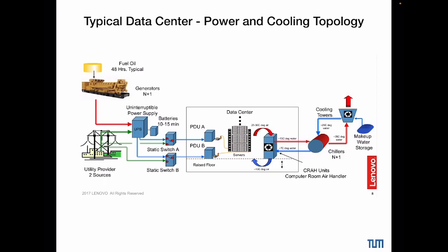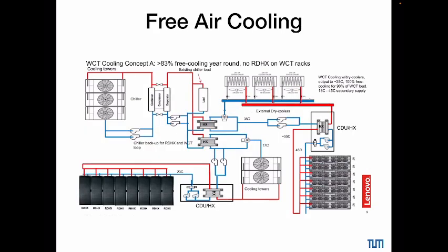Then there is a chiller, and we take out the energy to produce 7 degree cold water in the chiller with the help of additional electrical power, and then we get water at 35 degrees, which can be cooled on the rooftop with cooling towers. Then this water flows down at 29 degrees again, goes into the chiller, and that's the way to cool. So you put additional energy into the cooling of your data center.